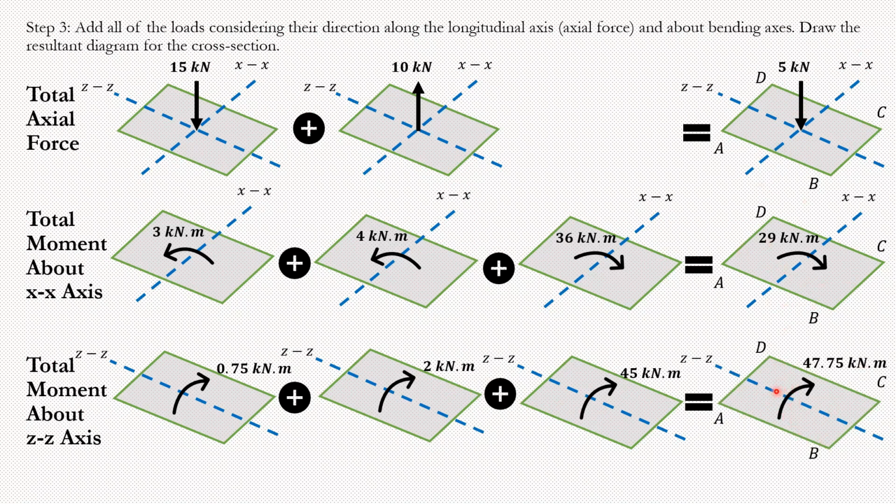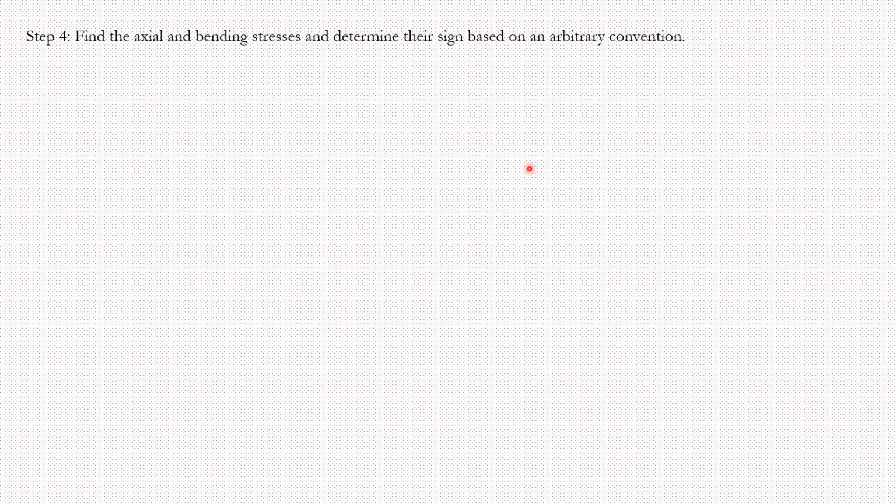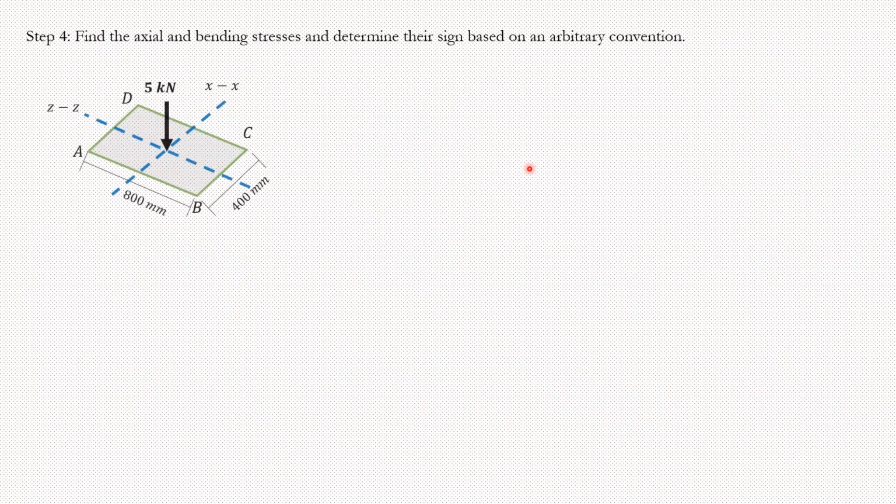Now we are prepared to kind of calculate all the stresses for the ABCD plane and add them together, right? The normal stresses, which includes the axial stress and the flexural stresses. So in this case, we're going to find the stresses one by one. So let's see how we can do that. For axial stress, what was the formula? It's just P over A, right?